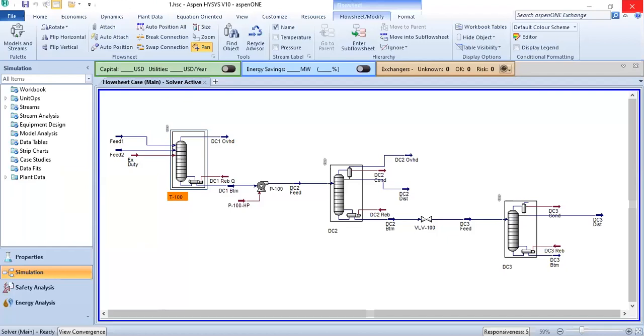There's another question saying that these steps are always the same. From what I understand, you asked about the steps of the distillation building. Yes, any distillation column follows the same steps. The only data you change is choosing the total condenser or partial condenser or no condenser, and the specs of the distillation itself, such as the ratios you want, or any fractions of a specific component you want. That's it.